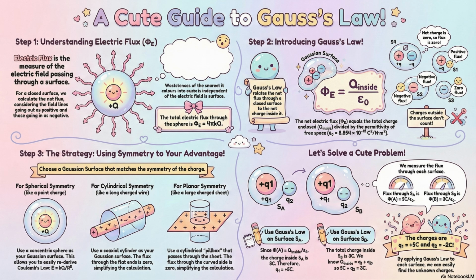From the slow death of dry out, let's jump to the sudden, spectacular death of the tantalum MnO2 capacitor. You called this one the firecracker. They are. Tantalum capacitors are incredibly dense. They're used everywhere, but they hide a massive danger. Their construction, a finely divided metal powder, tantalum, paired with manganese dioxide, is chemically very similar to a pyrotechnic compound. Wait, similar to a firecracker? That sounds like a terrifying thing to put on a circuit board.